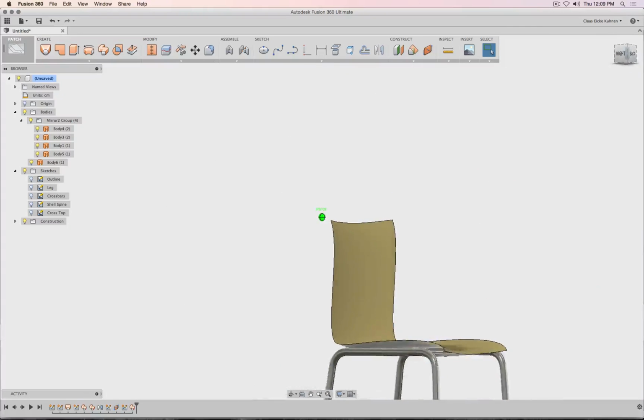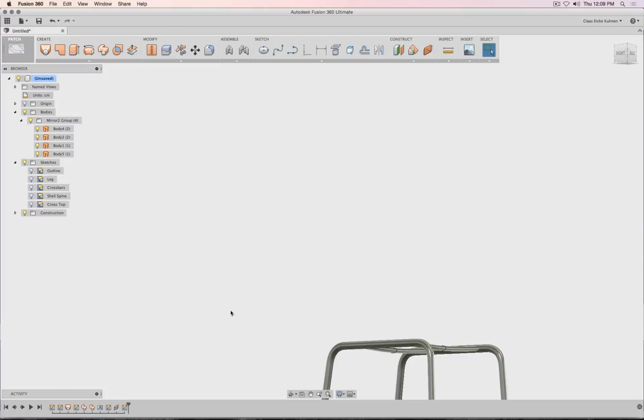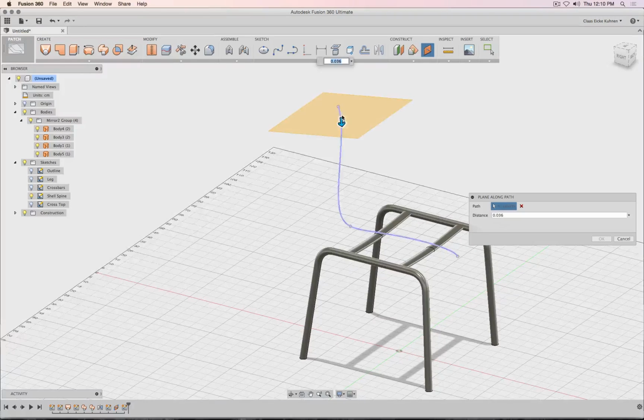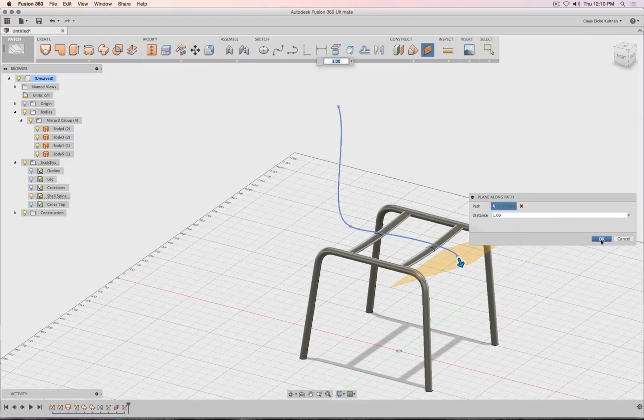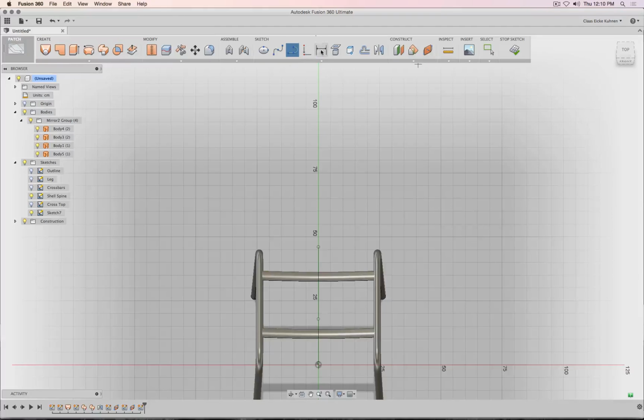Seriously, that wasn't too difficult. But let's say here I would like to have a little bit more control. Maybe this should be flat. So I need another profile there. So what I'm going to do, another path, another plane along this path to the end, a new sketch on there, 3D include this point, make a line from there, 20 and 20.